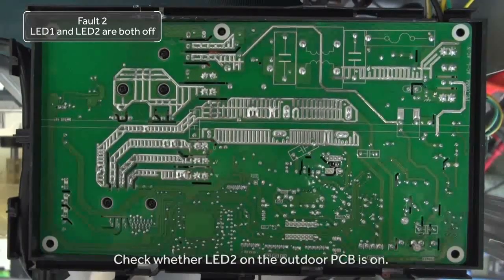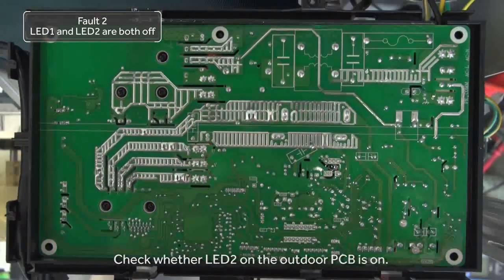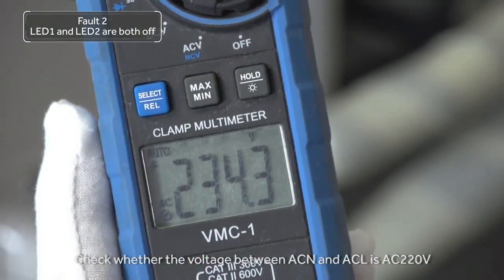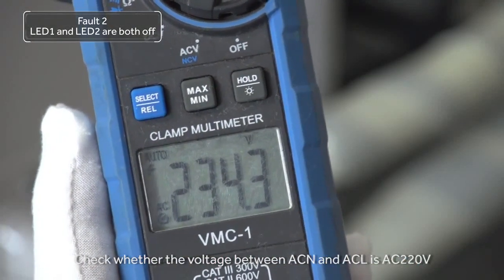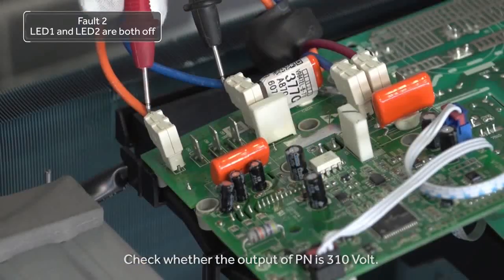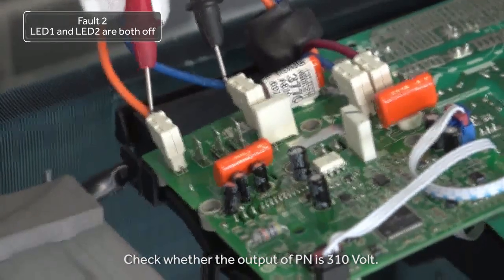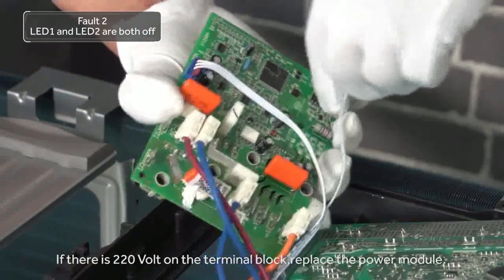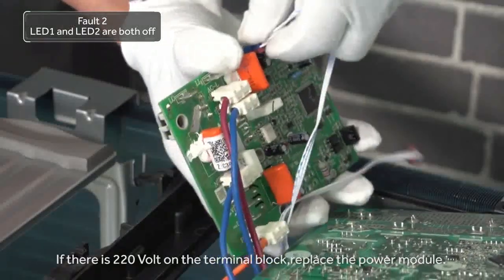Check whether LED 2 on the outdoor PCB is on. For individual power modules, check whether the voltage between AC-N and AC-L is AC 220 volt. Check whether the output of PN is 310 volt. If there is 220 volt on the terminal block, replace the power module.